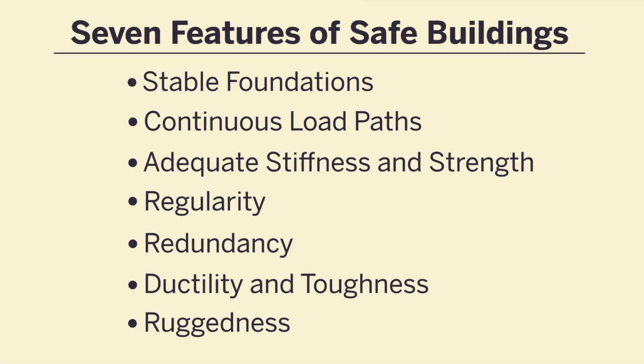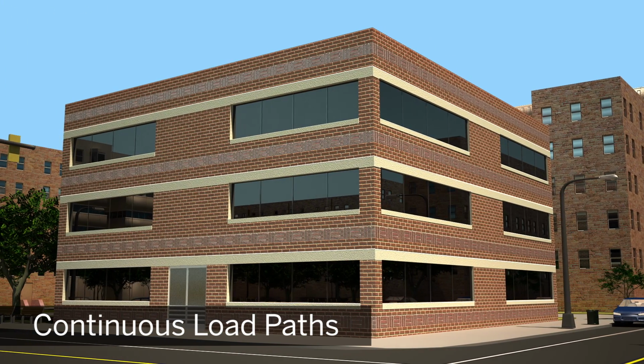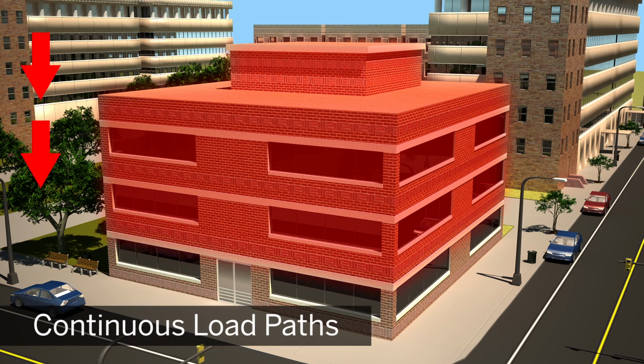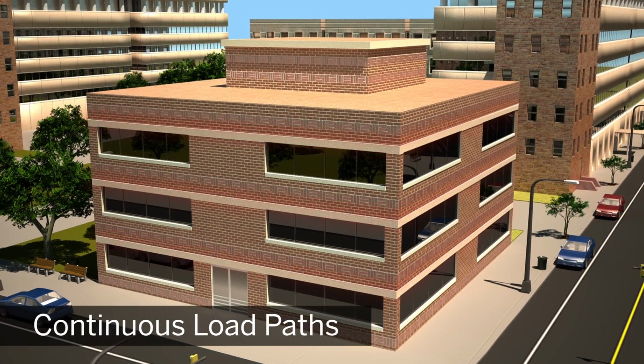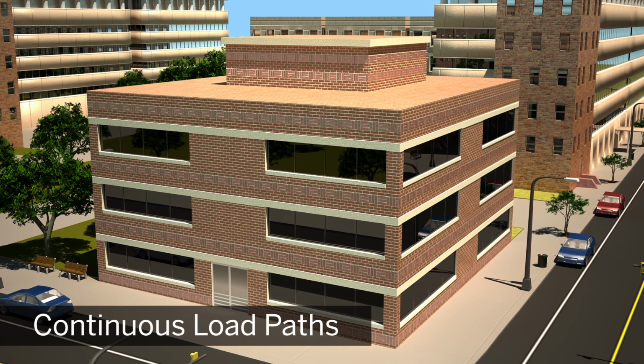It is very important that all parts of a building or structure, including non-structural components, be tied together to provide a continuous path that will transfer the inertial forces resulting from the ground shaking to the ground. If all the components of a building or structure are not tied together in this manner, the individual pieces will move independently and can pull apart, allowing partial or total collapse to occur.